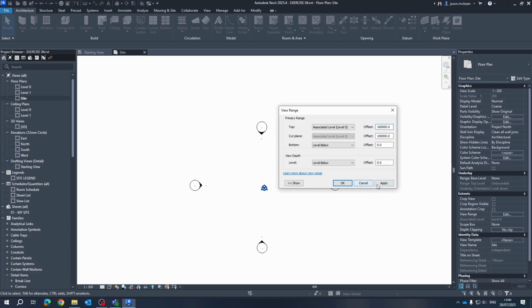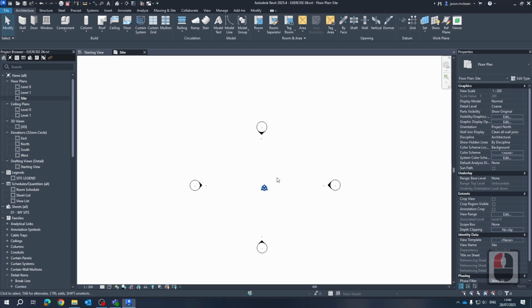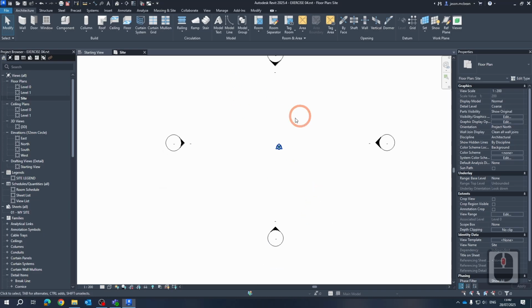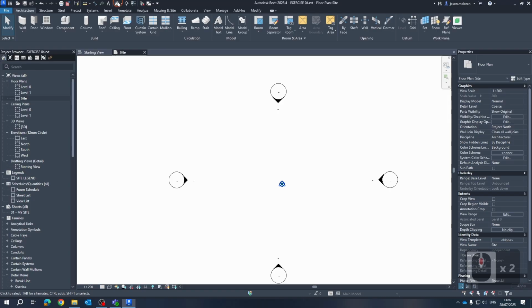This is quite a complex topic and a lot of people do it different ways. From office to office this will depend. It'll be very dependent on the office, where the site's located. What's interesting when you are doing topography is that sometimes the best workflow is to produce your topography in a separate model to your building model, so that you don't have conflicting levels that you need to manage the whole time.